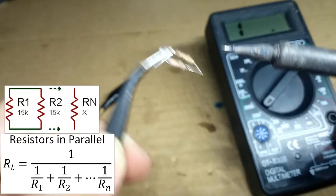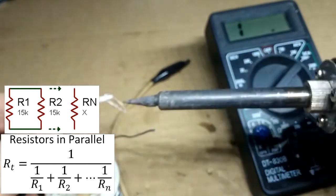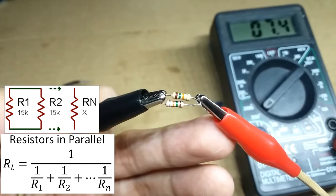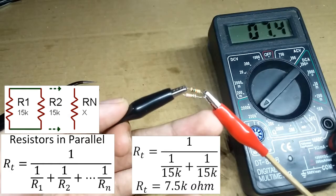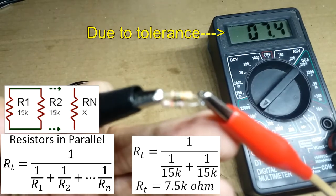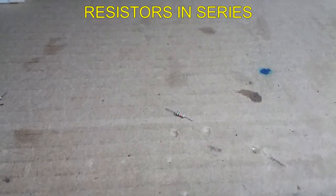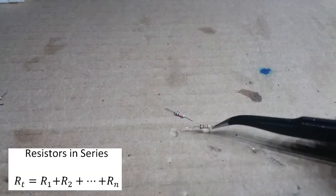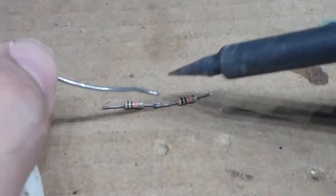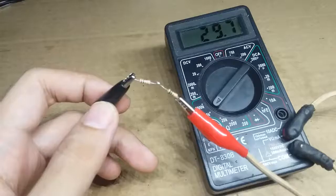Using this formula will determine the total resistance. So if I connect these two 15K in parallel, using this formula will result in a 7.5K resistor. You can connect resistors in series to add the resistance. So for example, if you need a 30K ohm resistor, you can just connect two 15K ohm resistors, and there you have it.